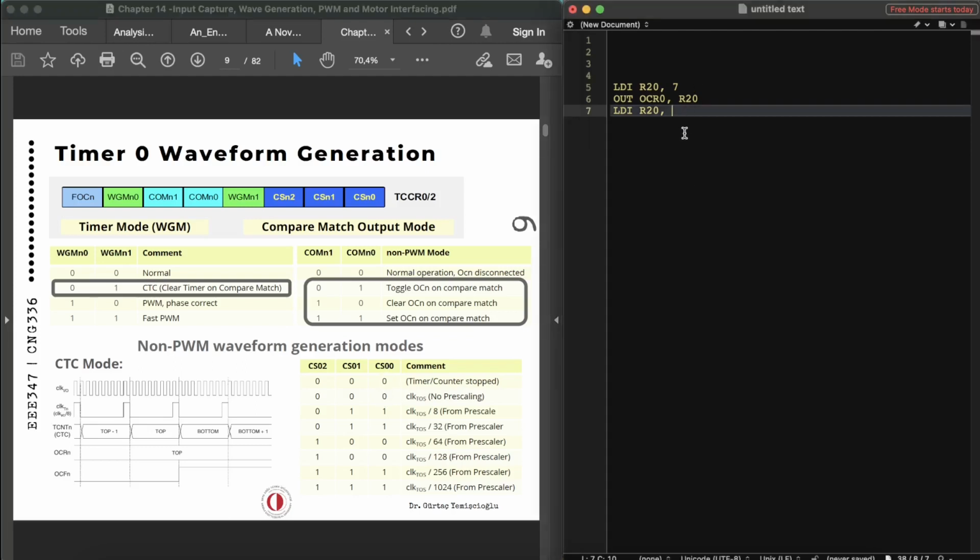So in this case, let's write down the TCCR first so that we can calculate the hex value. So it's 0 for WGM mode. It's in the normal mode or in CTC mode. Doesn't matter. So let's set it to 0. And then COM bits, it can be toggle. Is it normal or toggle? It didn't say anything, so we can use whatever we want.